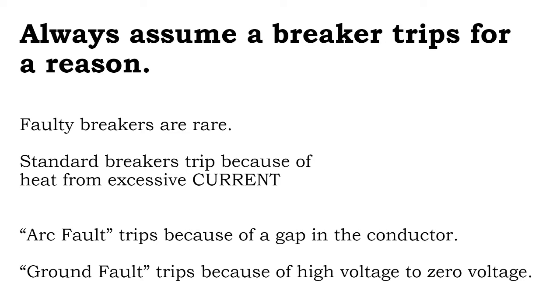If that breaker had tripped and you took a step back and said, okay, well, there's a 90% chance that there's something electrical wrong with the system, and so we need to figure this out before we let the system just continue to operate. This is real safety work. You can't just let a breaker that's tripped go uninspected.